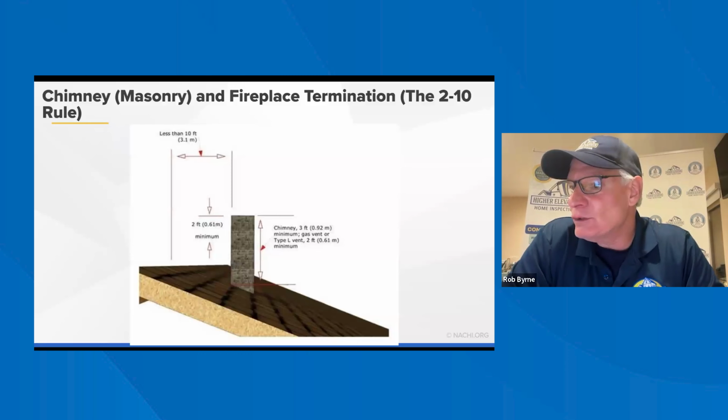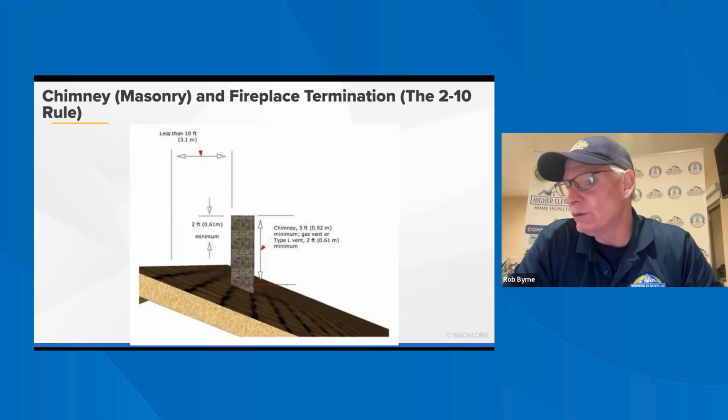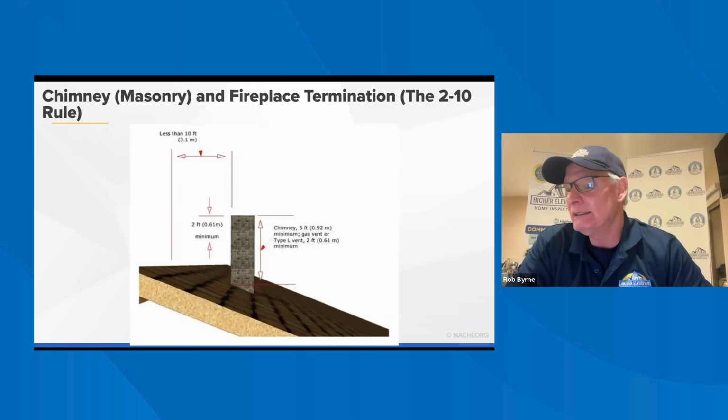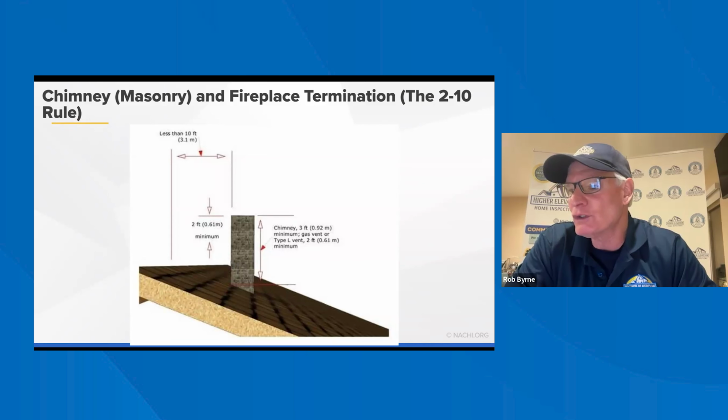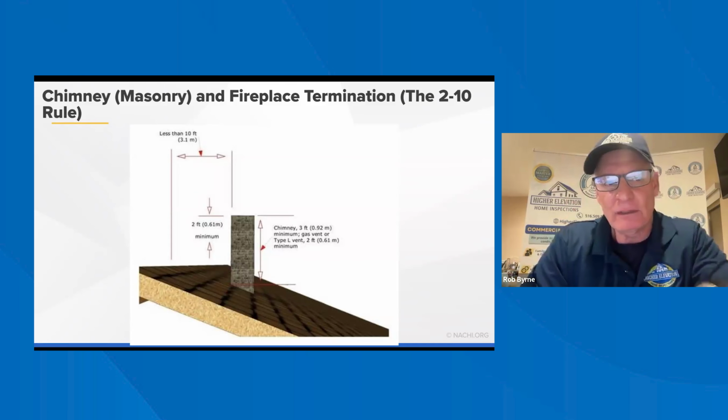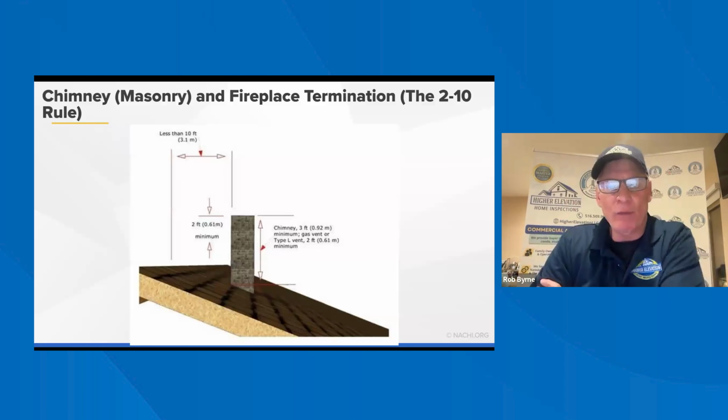It's a common mistake to apply chimney masonry termination height requirements, the 3-2-10 rule, to gas fuel vents, which causes vents to extend above roofs much higher than needed. In most cases, for example, gas vent pipe terminations above roof slopes up to 6/12 need to be only 1 foot high. Gas vents that are 12 inches or less in size and located at least 8 feet from the vertical wall or similar structure should terminate above the roof. This is kind of a good diagram of what we're talking about.